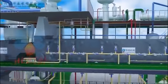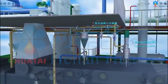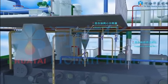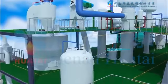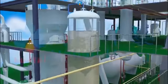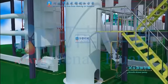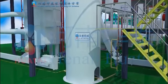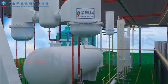It is pumped into the mixed oil centrifuge, then goes into the fixed oil continuous filter after removing the big impurities, and goes into the mixed oil temporary storage tank after removing small impurities of oil. The mixed oil is extracted by the extraction pump, goes through the crude oil counter, and is transported to the pre-evaporator.